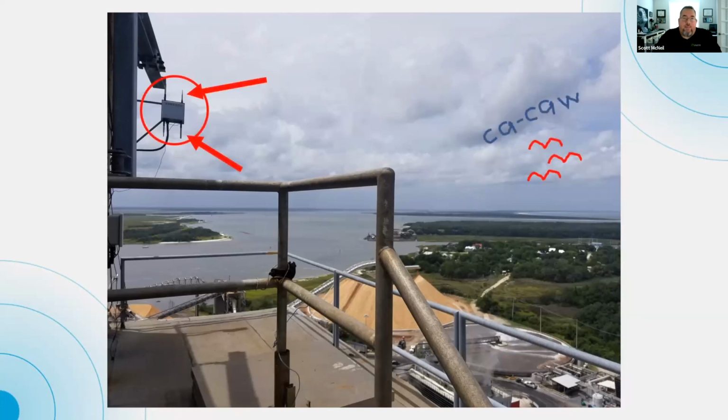So yeah, the big thing here is the antennas. These were 3 dBi and 5 dBi respectively for 2.45 gig. And how they expected that to reach 14 stories down off rubber duck antennas, I have no earthly idea. And I just spent 3 solid minutes harping on it. They weren't sealed, they were just screwed directly on. Pedro says that's not an outdoor AP as well.